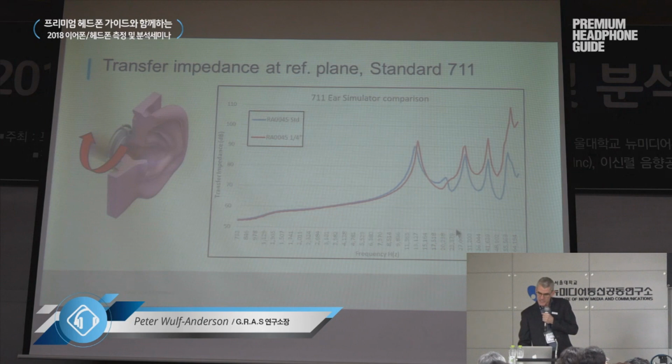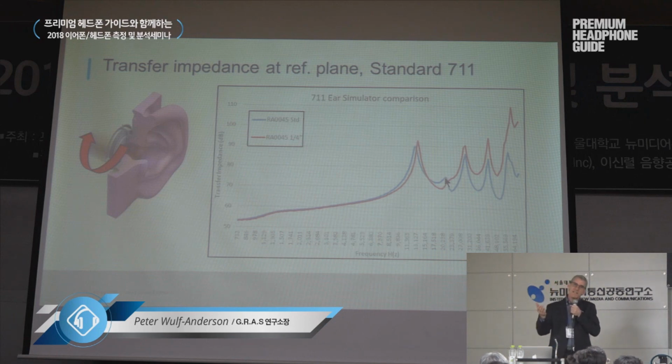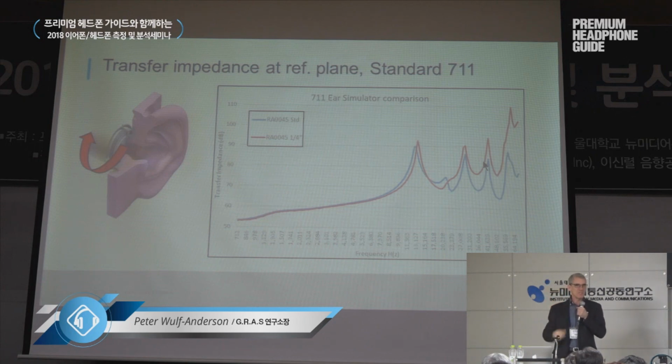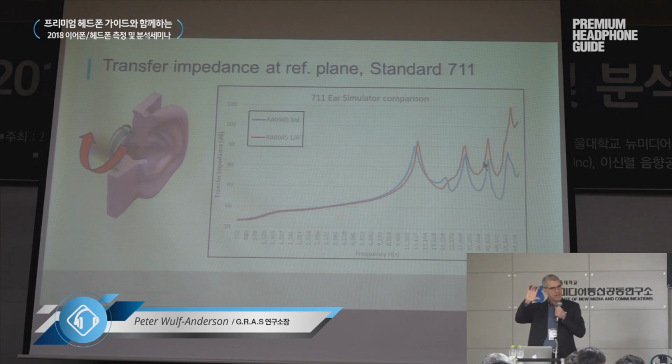As you can see, after 20 kilohertz, which is around this point here, there is still lots of output. Even with the half-inch microphone that starts rolling off, there's still output. Yes, it is dampened the higher you go in frequency, but you can even use a half-inch microphone to do fairly good measurements up to 40 kilohertz. Yes, it's dampened, but it's a very well-defined roll-off.